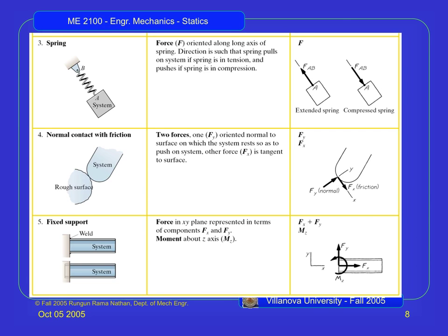All right, so this last one here, number 5 at the bottom, is what we've been talking about all along. This is the last thing I want to go over for this topic. When an object is cantilevered or fixed into a wall, this is what's happening. This actual system, you could draw it with a weld, see they put weld there, or you could technically extend this into the wall to show that it's actually embedded in the wall. If an object is embedded into a wall or into a support, it cannot rotate freely this way. The end of it, yeah, sure, that can fluctuate, but this end cannot move. It's literally fixed. And if you've tried this with the diving board, jump on one end, the other end should not move at all. Okay, it should be fixed in. So this should be fixed, so that's why you see this moment Z. And the moment Z right there.